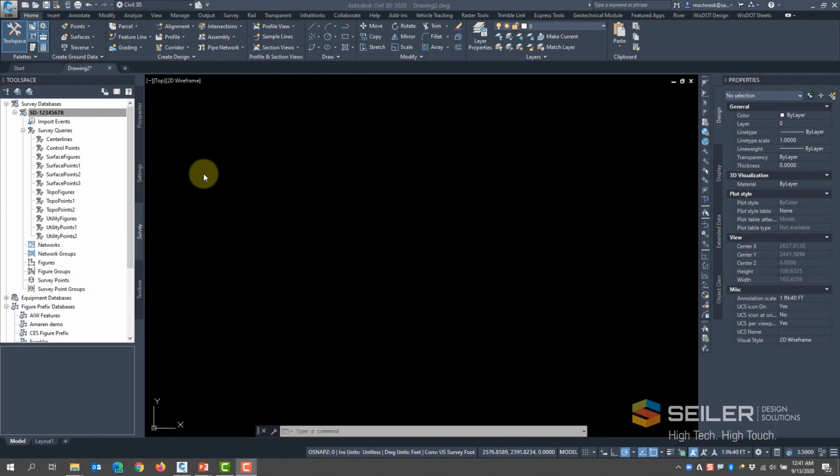Okay, let's put it into practice here. We have our survey database open. We're ready to import our data. I am using the correct template that has the point codes, the descriptor key set, and the figure prefix database, the survey figures. So let's go ahead and import some data.